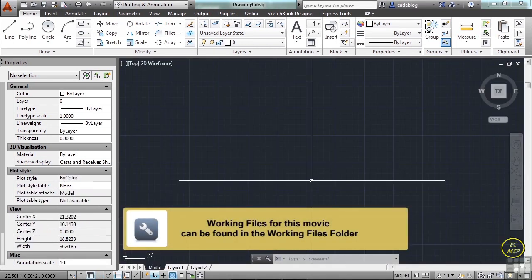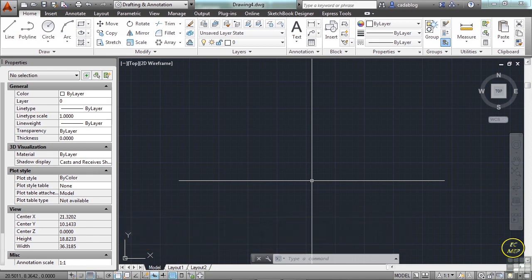Making a design in AutoCAD is more than just drawing lines and circles. It's a complex process that has been developed so that we can create complex designs. One of the keys to efficient CAD work is to organize your data. Model space is meant to be a three-dimensional area in AutoCAD and a two-dimensional area in AutoCAD LT where you can draw and create your design. Your design needs may not include three-dimensional models, only two-dimensional, and that's fine. But regardless of how many dimensions your design requires, the model for it belongs in model space.